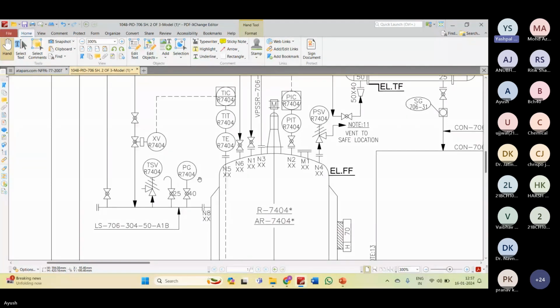Before crystallization, that material was transferred from one equipment to the crystallizer, and at normal temperature that material mass was in a semi-solid condition. So we were putting steam tracing on that line to maintain it in a liquid state to transfer to the crystallizer. We were trying to find out why it was reducing the yield by 4 to 5%, and it was costing around 200 to 300 rupees per kg. So we tried everything, but we could not find the solution.